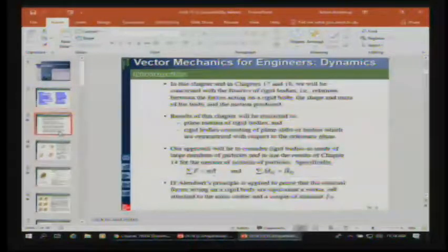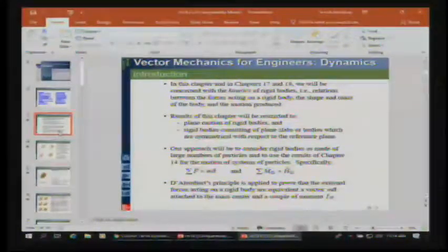So the first part of this is we always go back to Newton's second law, force equals mass times acceleration. It's the basis for everything in kinetics. And the other equation is built directly upon that idea, where the summation of moments on a rigid body is equal to the rate of change of angular momentum. Now, the important thing to notice is that for moments, angular momentum, and rate of change of angular momentum, we always have to state where we're taking the moments about, where we're measuring angular momentum from.